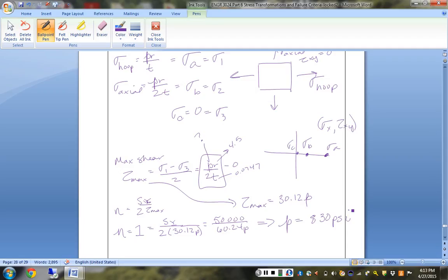Now, it's expired, so I don't know if we really want to do that or not. I wouldn't really want to hug that close on the edge of material yield either, because that puts trust in the welds, that puts trust that it hasn't been dunked or dinged or rusted or anything. But we also don't have a compressor that can do more than about 85, so we're probably good. So this is what we expect to be able to put into it using the max shear criteria.